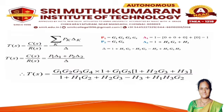Then we have to determine the transfer function of the system. T of S is equal to C of S divided by R of S. We know the formula. We have to apply P1, P2. We have two forward path gains, so K is equal to 2. It is P1 delta 1 plus P2 delta 2, divided by delta. We know all these values, so we substitute them and then find the transfer function of the system.